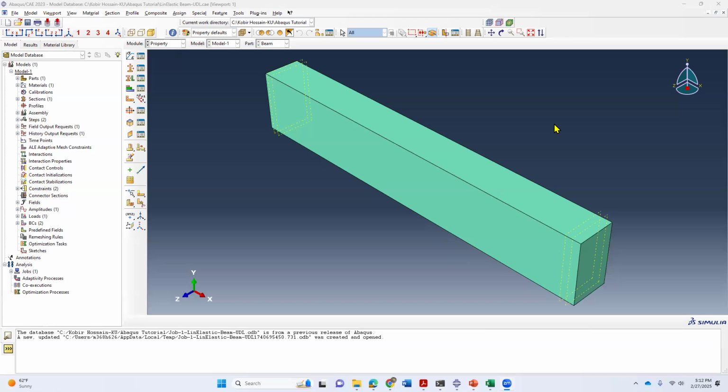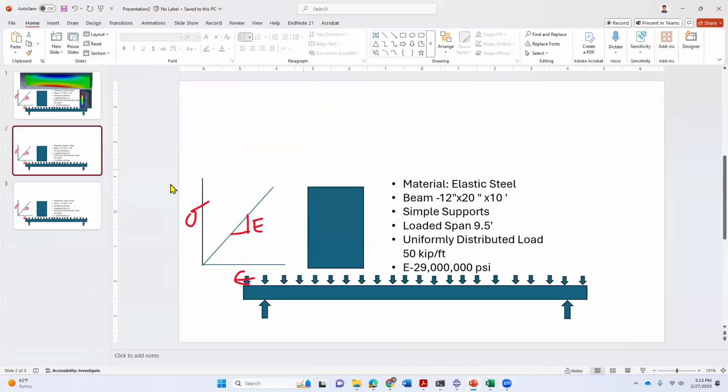The stress strain response for steel. So we don't have the test result. So what we can do is we can assume the steel to behave as linearly elastic and linearly plastic. So it's like a bilinear elastic plastic material. So to do that, let me discuss where we stopped in last class with the linear elastic beam.